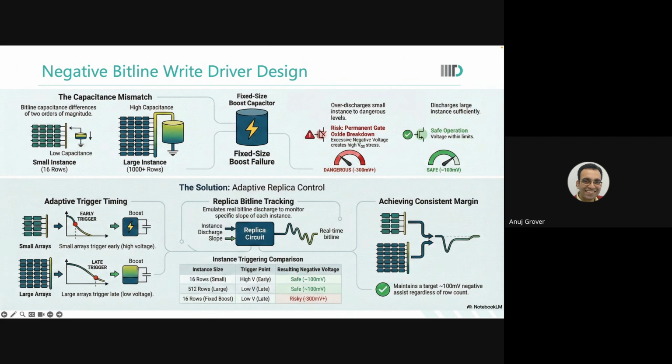Now let us say this capacitance was smaller. Let us say this was 0.2 or 0.4 picofarads, much smaller. Okay. In that case, if I had taken this to 0, what would be the final voltage? Minus 0.24 upon 0.6. Are you with me? This is a risky voltage. This would lead to breakdown.